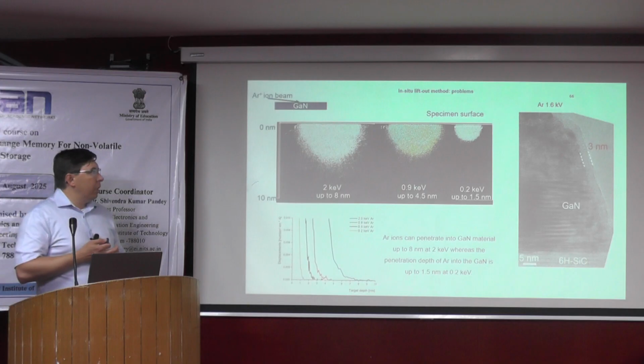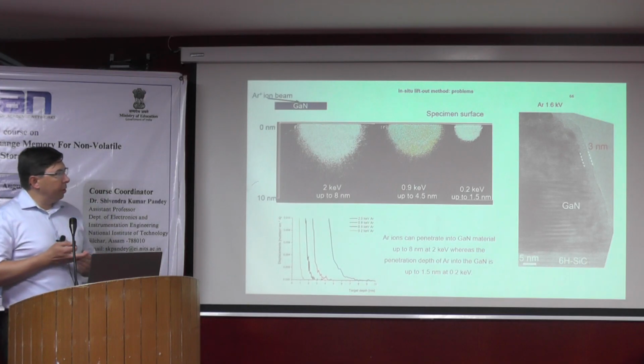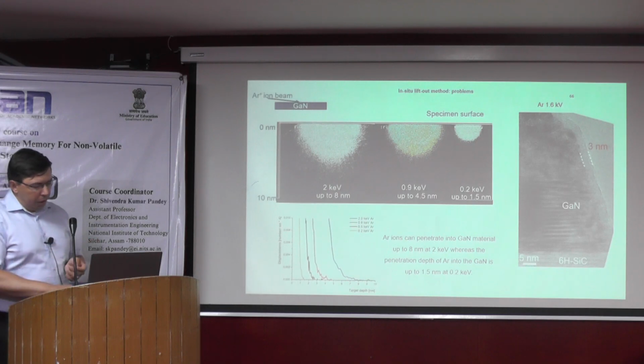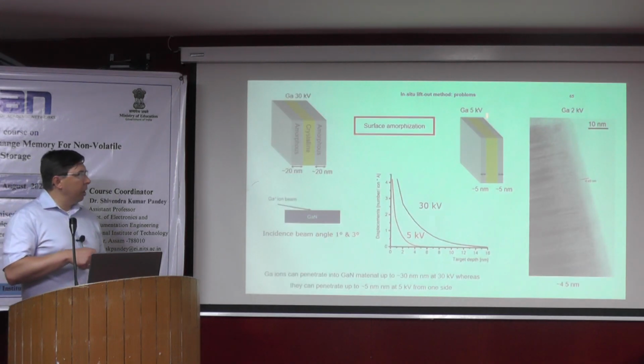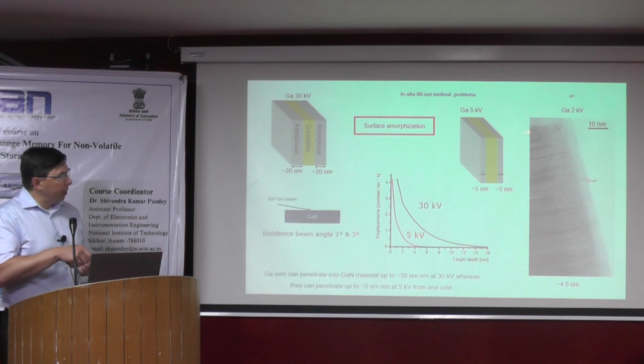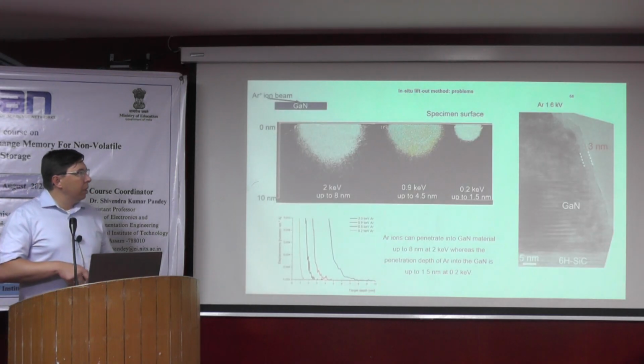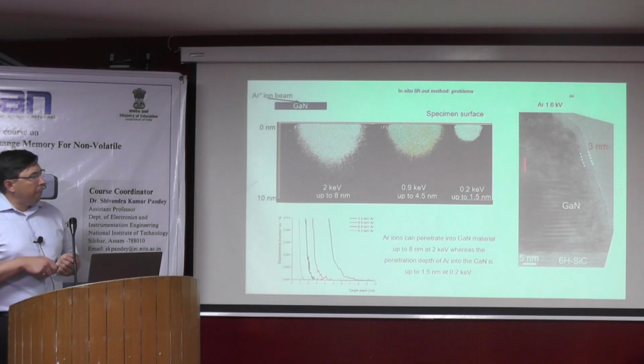nanometers. So here we also tested on our samples, on our TEM specimen. First we prepared the specimen by the standard FIB approach, and then we also used low energy gallium ion beam polishing at the end, and then if we use argon ion beam polishing, then we can reduce the amorphous surface layers even to the low value, to 3 nanometers.